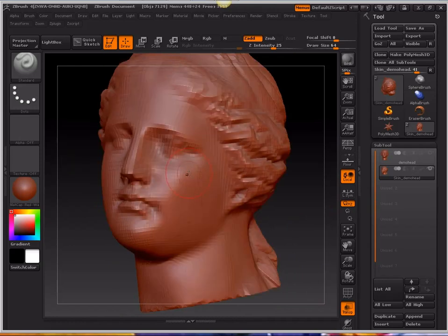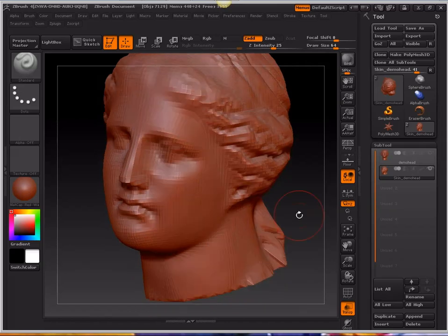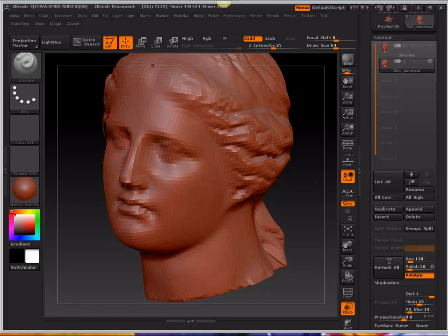But for the purpose of taking this sample, this conversion from the scan into T-Splines, you don't want to have millions of polygons, because you're going to really tax your hardware inside of T-Splines. If you want to make sculptural changes, you can make them here. If you're doing a straight reverse engineer, you can dial this all the way up to 1,000,000 polygons and reproject this onto your mesh, and you'll get a nice, tight representation of the original scan.